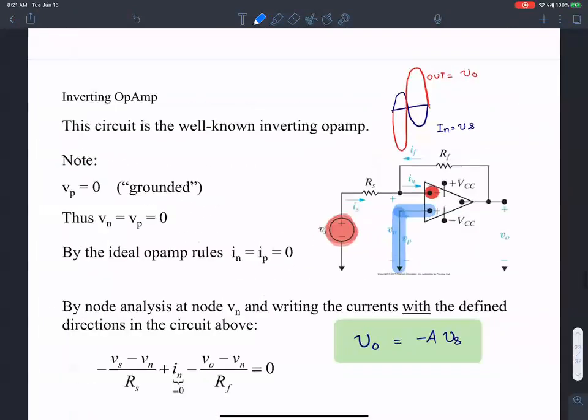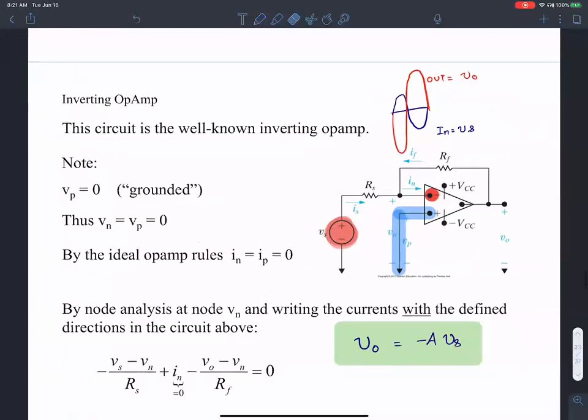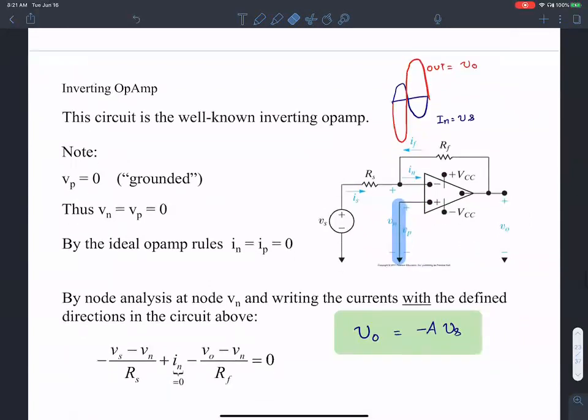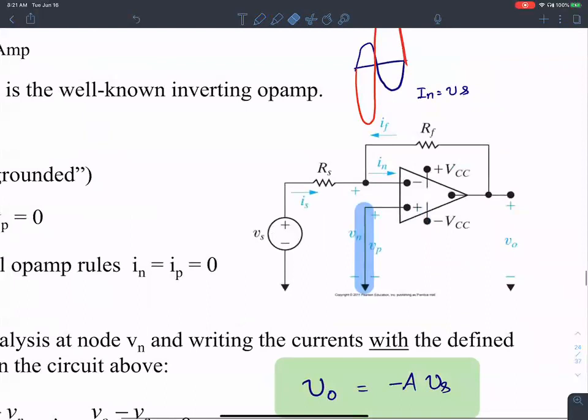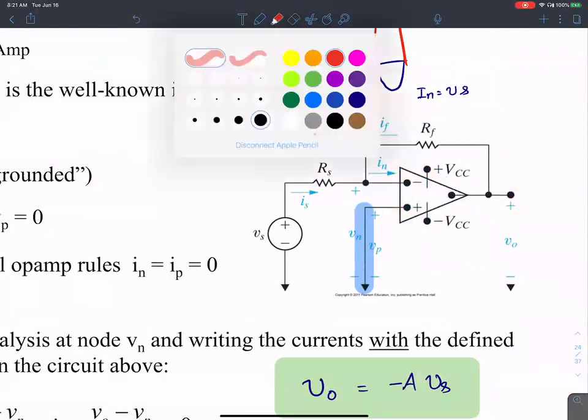Now what I'm going to do is put circuits around the op-amp. Like I mentioned in the last class, this is called an inverting configuration. First of all, let's pay attention to something. So far we have only seen an open loop configuration where an op-amp input is applied like so, and the output is gain times the input. But here, something different is happening.